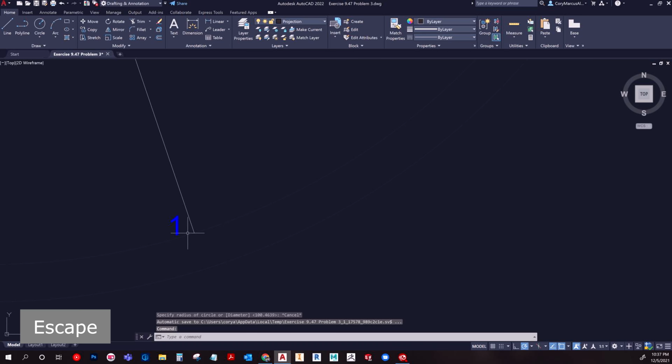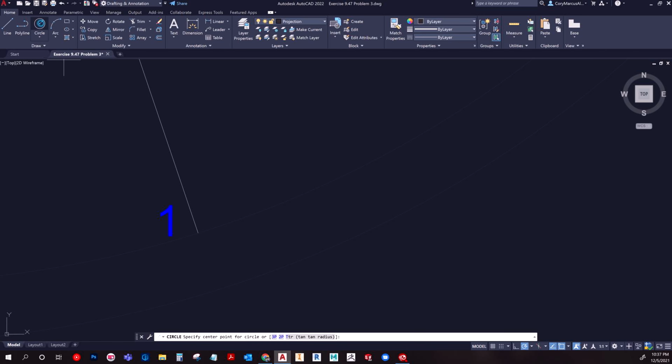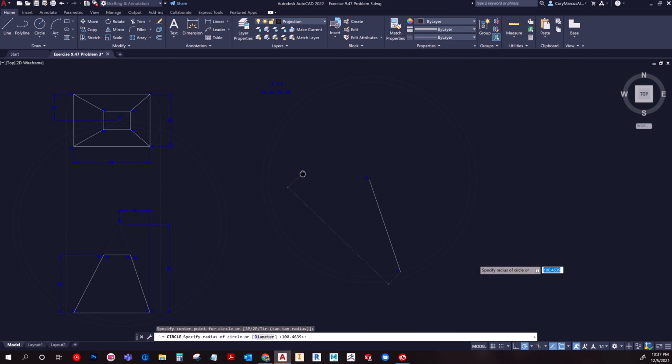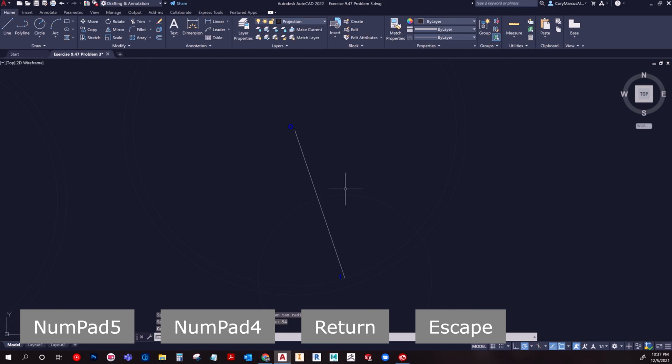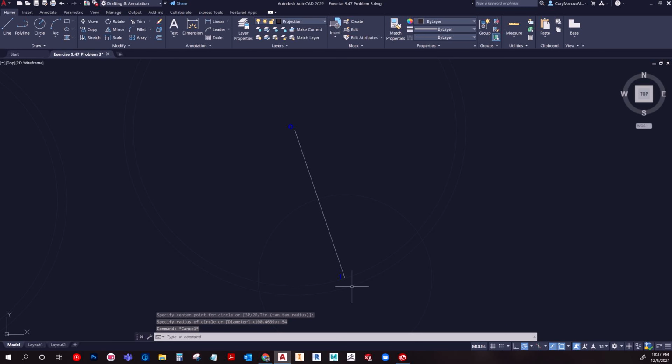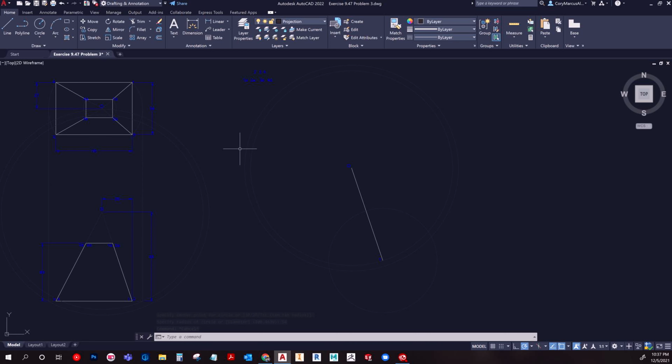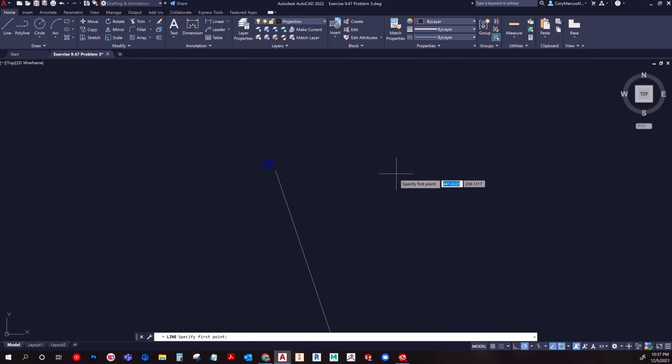So the idea is you go to the end of this line, turn on your radius circle, and you will give that value. So 54. So now, when I connect to this next one, the distance between the 2 points will be exactly 54. It's a really cool little life hack that I really necessarily didn't know about. But yeah, so that was edge 1.